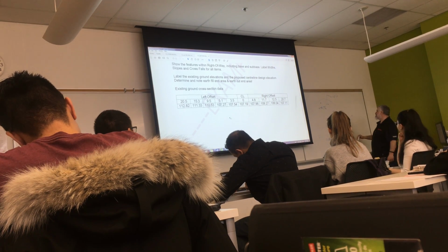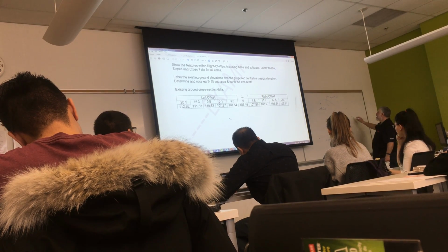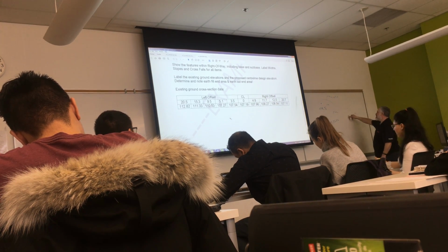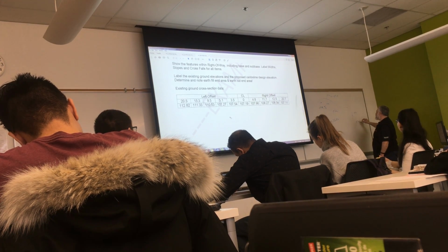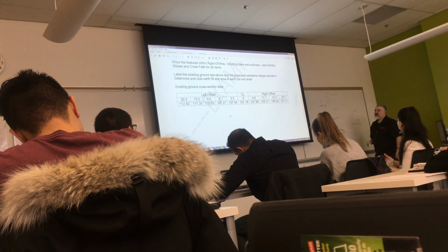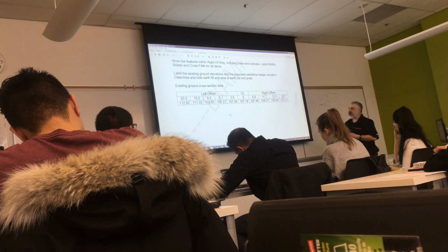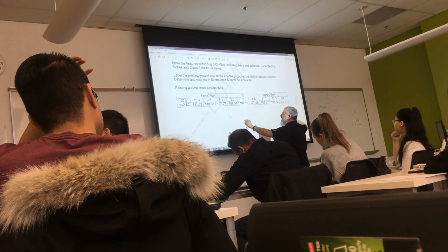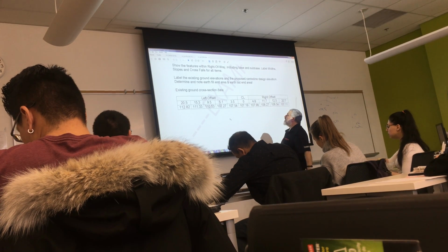And the last two pairs that go together are the offset, how far from center are you, and the elevation. So that's what we're plotting in the cross section. Okay? So when you're plotting this information, you see offset and you see elevation below. And you have a left and a right, and it's all laid out spatially relative to center.